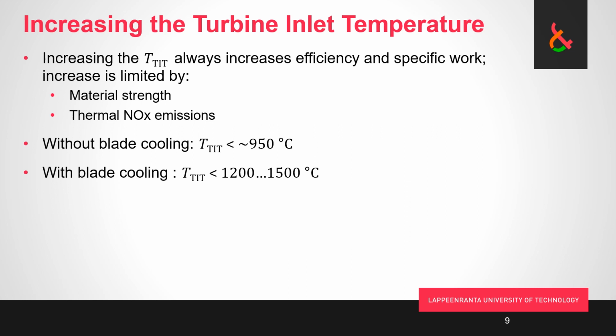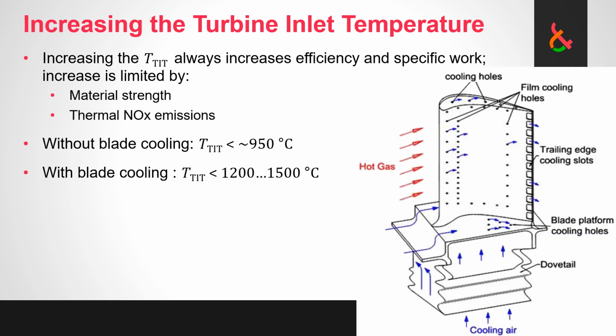The question is, how do we do blade cooling? And the answer is we kind of looked at that already with those internal airflows. Our first turbine stage blades are typically hollow. They have tiny little holes in the blade, and air comes through the also hollow shaft, through here. Our air is going to be at higher pressure because this air did not come through the combustion chamber, where we always have pressure drops.